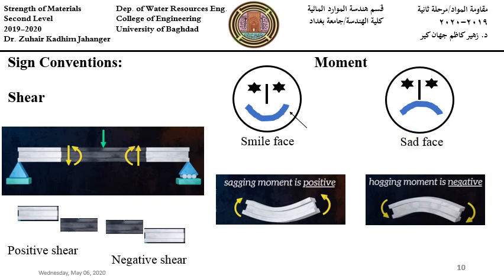for sad face. So in calculating shear force, upward acting forces or loads are considered as positive. A positive shearing force tends to move the left segment upward with respect to the right, and vice versa. You can double check your textbook on pages 108 to 110.